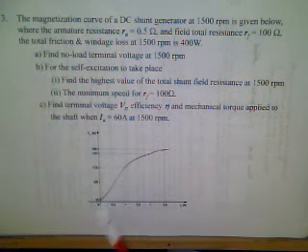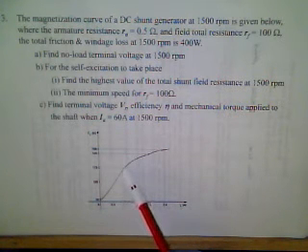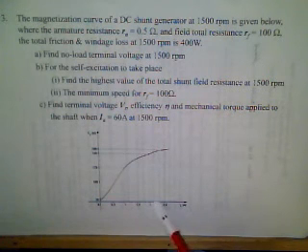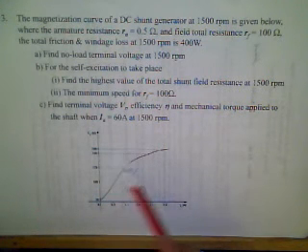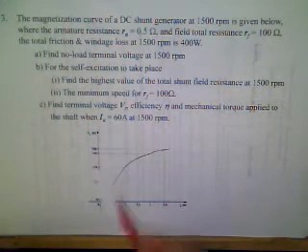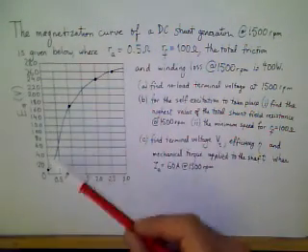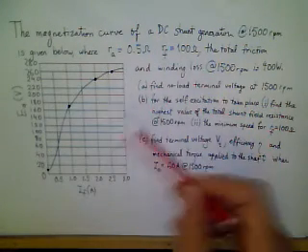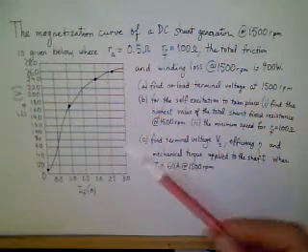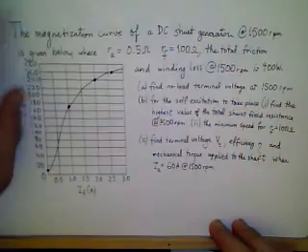So the magnetization curve is as follows. 10 volts is the no field current induced voltage. At about 1 ampere of field current, we have 170 volts E_A. At 2 amperes field current, 240 volts, and at 2.6 amps field current, we have 260 volts induced voltage, given in a graphical representation. The same graphic is given in a more scaled form, with straight lines and divided squares, drawn by hand. The problem was written during the classroom lecture, so it's the same as the slide text.